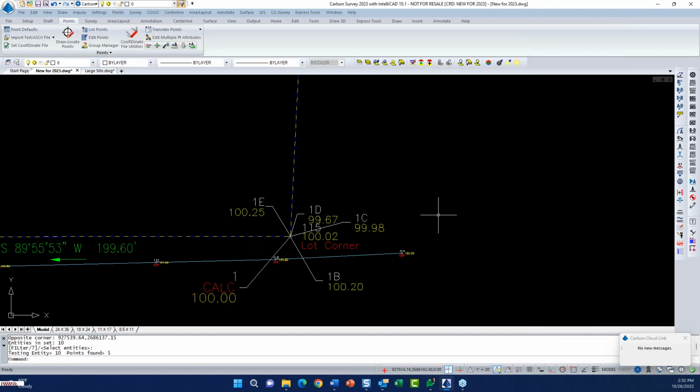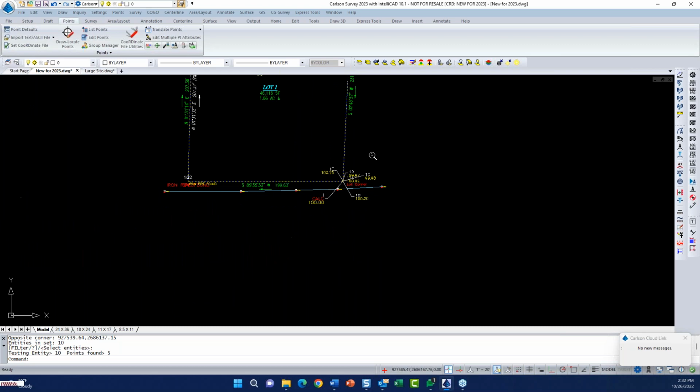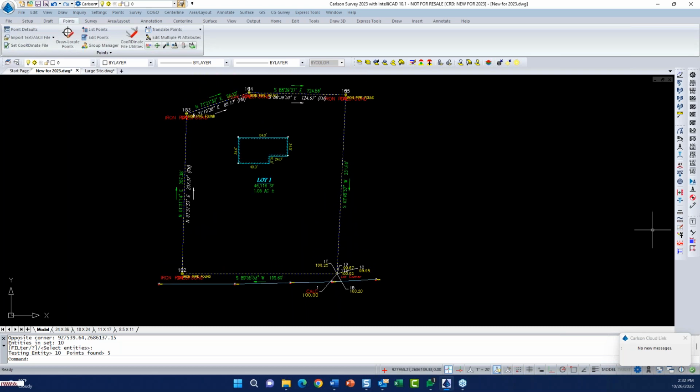So that is an improvement over an existing command. Prior to this release, what you got was a residual that was in 3D. So if you were really not paying attention to your elevations, it was really hard to tell how close your connection was between the other points, because if you had a bogus rod height in there on a corner and all you wanted was horizontal, well, you got the vertical information whether you wanted it or not. So I am particularly happy with that little upgrade.